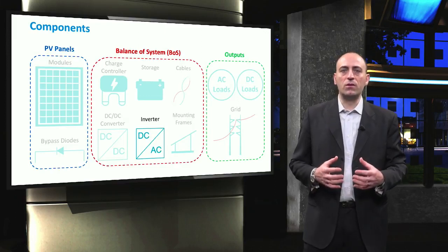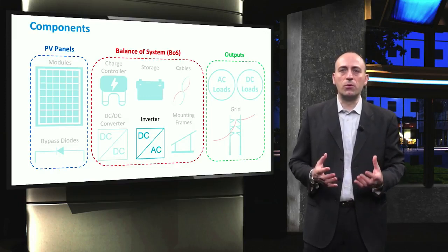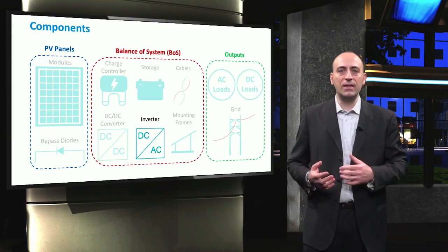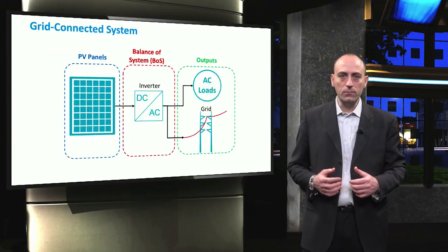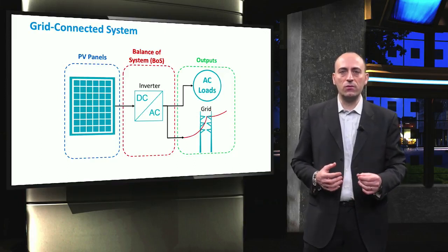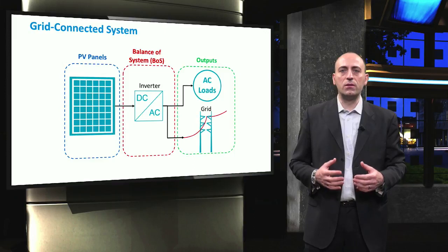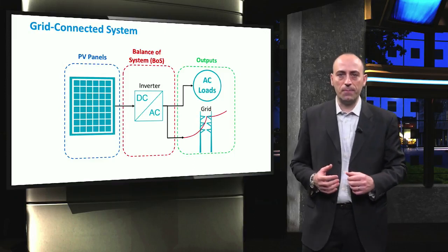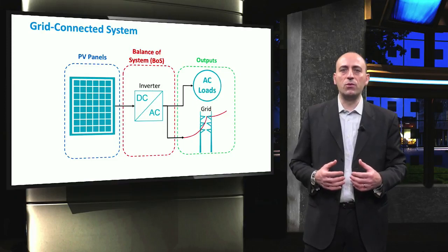Secondly, the term inverter is also used for the total unit produced by manufacturers, and thus, depending on the application, it may contain an MPP tracker, a DC-DC converter, and a DC-AC inverter. In grid-connected systems, the inverter is connected directly to the PV array and converts the DC electricity coming from the PV array into AC electricity. Besides, such an inverter usually contains an MPPT system.